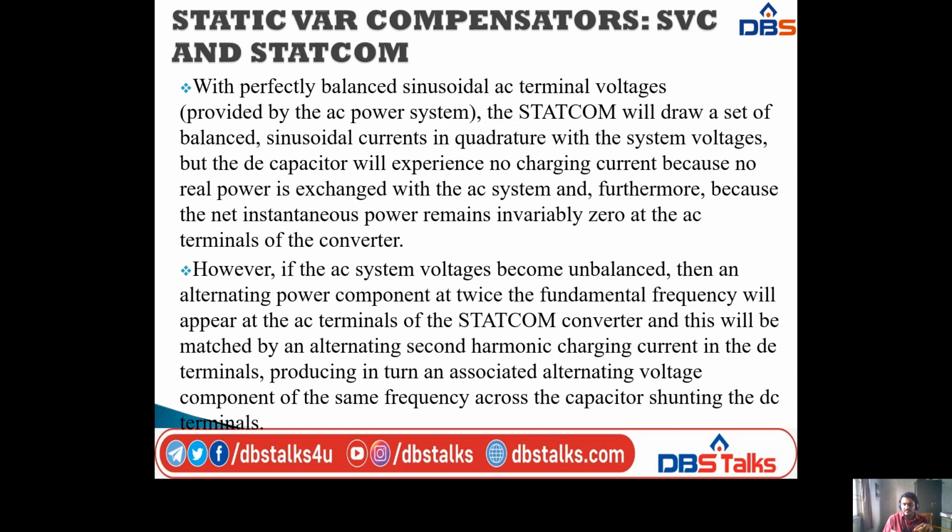However, if the AC system voltages become unbalanced, then an alternating power component at twice the fundamental frequency will appear at the AC terminals of the STATCOM converter, and this will be matched by an alternating second harmonic charging current in the DC terminals, producing in turn an associated alternating voltage component of the same frequency across the capacitor shunting the DC terminals.